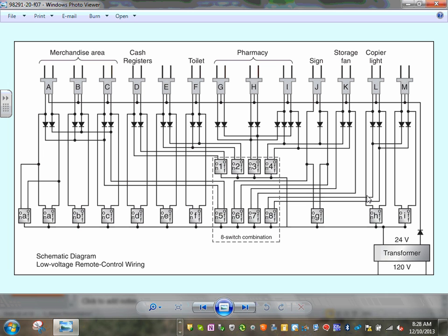And then here's the source of the low voltage system. Here's all the low voltage switching. Here's all the relays, high voltage section of the relay, low voltage section of the relay. The same thing for the relay, guys. Can you see that all the relays take one common, and then every relay has to have 2 wires. So how many wires do you need for 10 relays? No problem, 10 times 2, 20 plus 1 common, 21. And all these wires, guys, are gauge 18 or gauge 16.